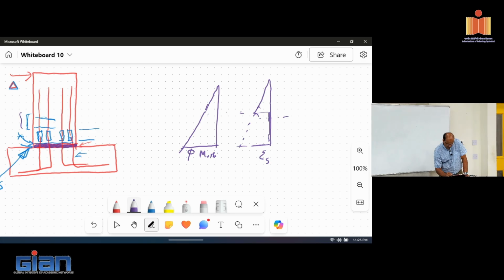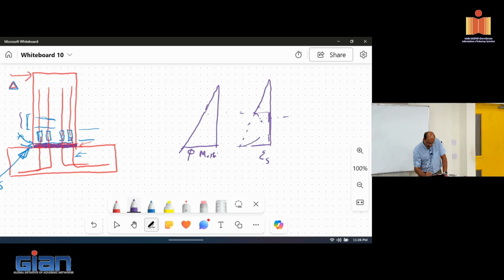There's going to be some development length, and your value is pretty high, so it will go down to some lower values and then come up again. Your curvature is reflected by your strain profile, and curvature dictates the displacement. So if I'm targeting the same displacement, I need higher curvature to match the same area.